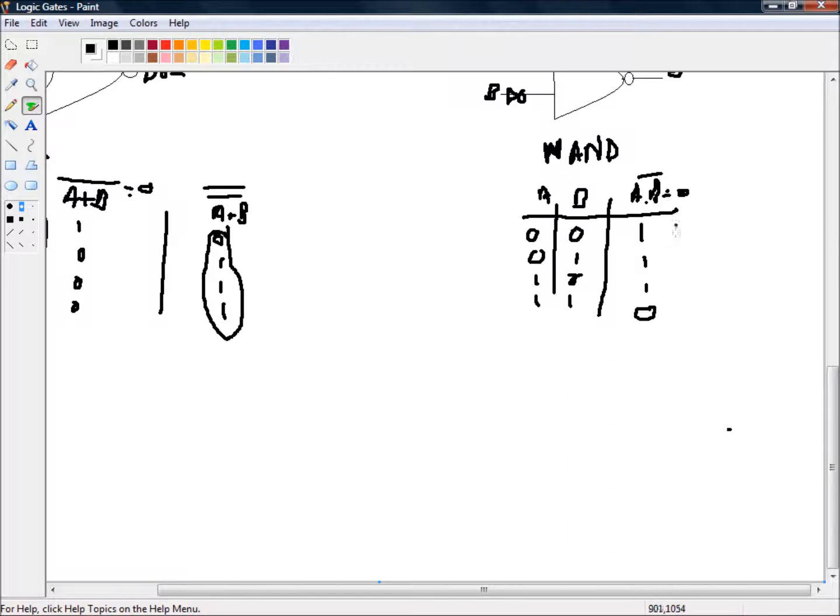So here we have our NAND truth table. What we're going to do with this now is NOT the two inputs. So we have NOT A and NOT B. And this output now will be NOT A and NOT B, which you might already remember from De Morgan's law is actually A or B, but we are going to prove it.